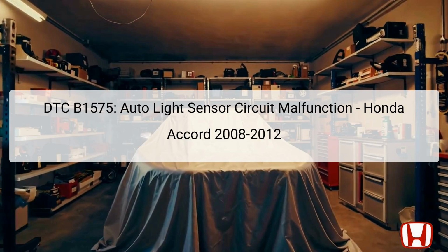Honda Accord models from 2008 to 2012 may encounter Diagnostic Trouble Code, DTC B1575, indicating a malfunction in the auto light sensor circuit. The auto light sensor plays a crucial role in determining ambient light levels and signals the vehicle's automatic lighting system accordingly. It is typically located in the upper part of the windshield, allowing it to effectively measure outside light conditions.